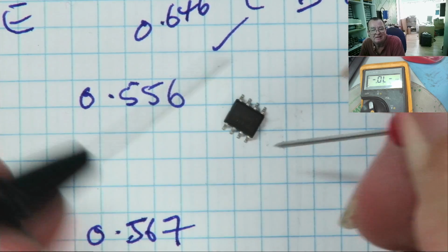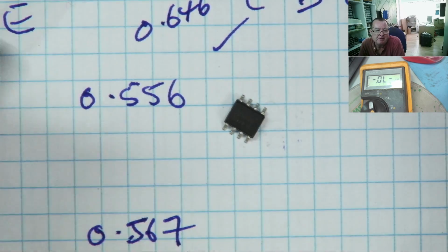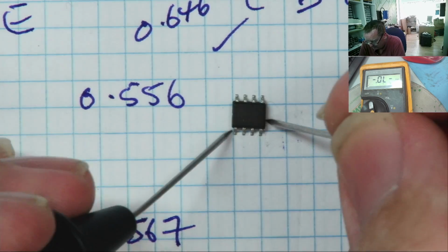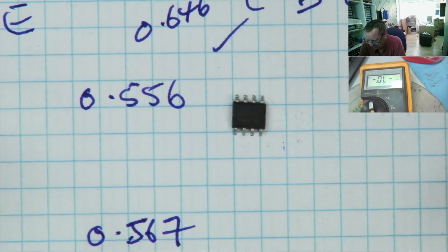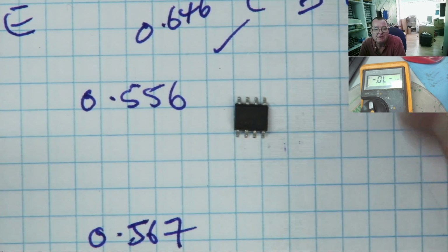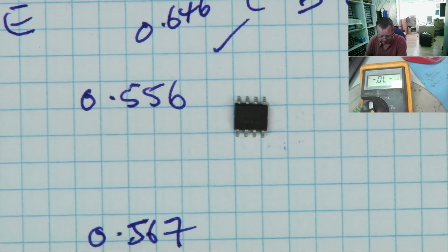So we know the negative switched it on. We know it's a P channel MOSFET because you put a negative voltage or a 0 voltage on the gate compared to the source to switch it on. So we know what it is. So that's how we measure those.